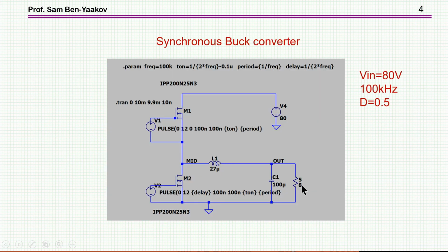So here is a simple, basic buck converter. It's a synchronous converter, two switches. Here is the inductor, output capacitor, and this represents the load. And the point is that we do need an inductor for proper operation of a PWM topology. You can look at this inductor like a filter that is filtering out the pulses while these are toggling, and to provide a DC at the output.